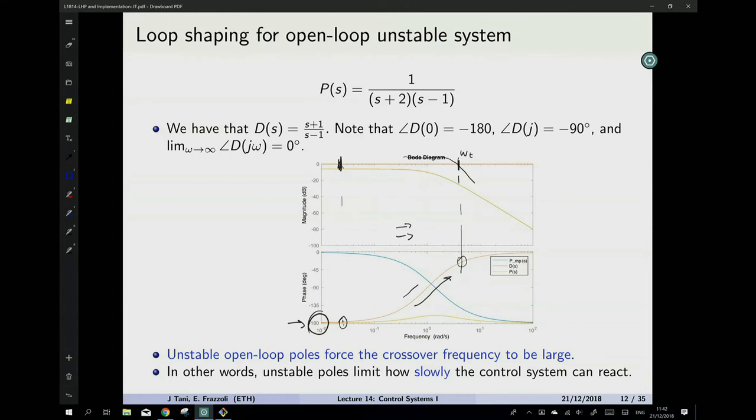So depending on the actual plant, typically figuring out the model requires experiments. And experiments, like all things that belong to the world of physics, have uncertainty. So you'll always be given, in real world scenarios, plants with uncertainty. So imagine you have this very small bandwidth where you need to make things happen, and you're not even really sure about what the location is, because you know, plus or minus, whatever it is, the accuracy of my instruments. So that's where the challenge comes out, okay?